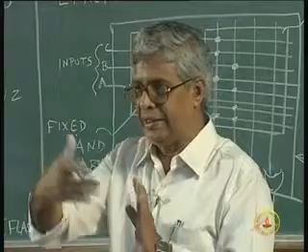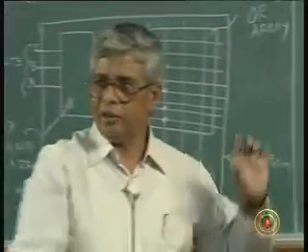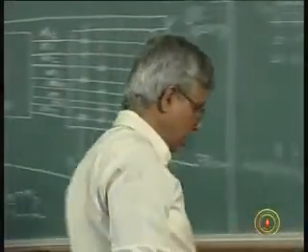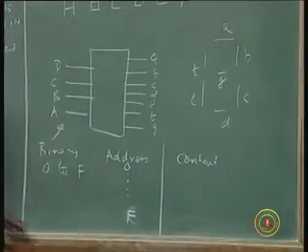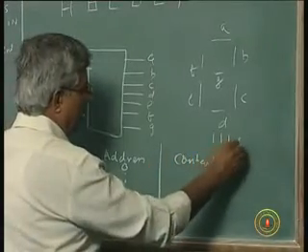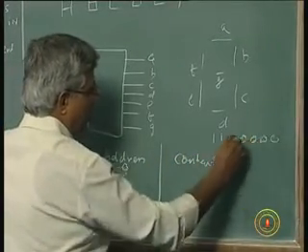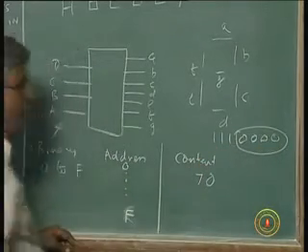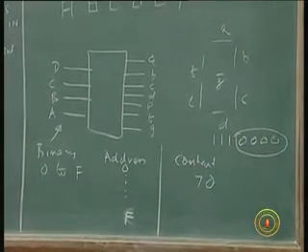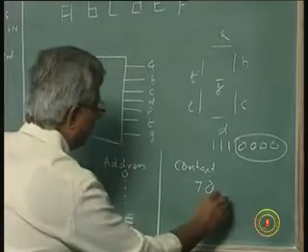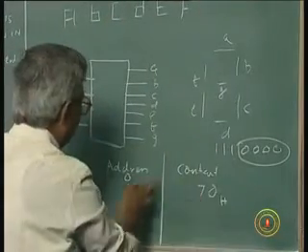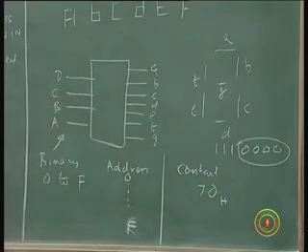First 4 bits, LSB, 1 hexadecimal digit. For example, if we have the number 111 0000, this is 0, this is 7. Isn't it? This is called hexadecimal 70. Like that, for each of these, I want you to get the corresponding hexadecimal.